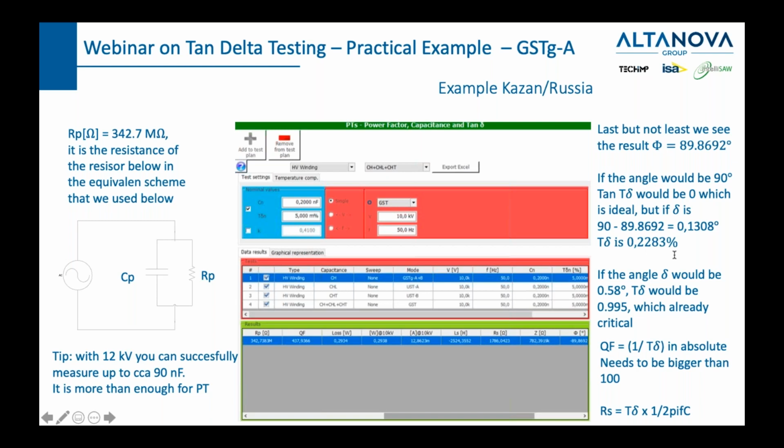Mr. Pablo, hi, one question. For a complex transformer like a PV transformer, double winding out, but with an electrostatic screen between the high voltage and low voltage windings, how do you suggest to do the test? Does it make sense to measure separately low voltage windings with a single high voltage and electrostatic screen, vector groups D, Y11, Y11? Thanks a lot.